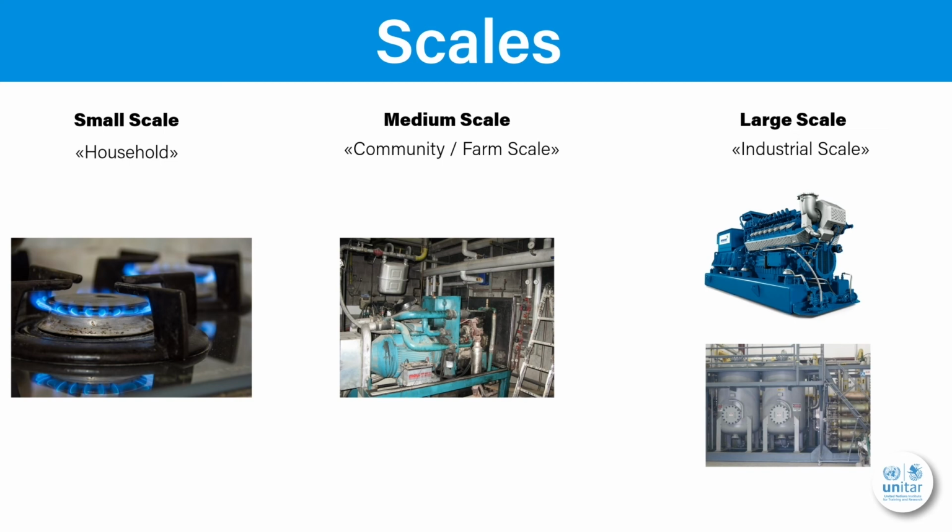At industrial-scale systems, we can also find systems that don't burn the biogas in engines, but split the methane fraction out of the biogas, using specialized membranes. We then have almost pure methane, which is basically natural gas. The biomethane is either injected into a natural gas grid, or bottled and sold. As a byproduct, we get carbon dioxide, which can also be used by other industries. Now we have seen what can be done with the biogas produced at various scales.